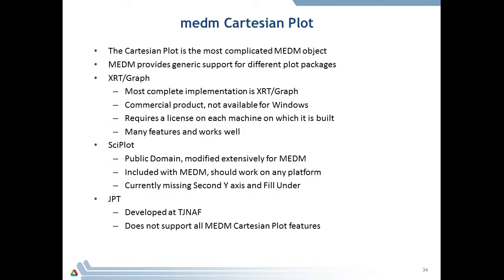The last thing I'm going to talk about today is Cartesian plots. The Cartesian plots are the most complicated of the MEDM objects. So we have different plot packages that we use for MEDM. The SciPlot was public domain and modified extensively for MEDM, and it should work on any platform. It doesn't have a second axis and the fill under. And so there's a commercial package that we have called XRT graph, which is more popular for MEDM Cartesian plots. It's not available for Windows.